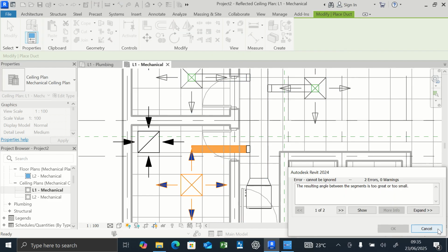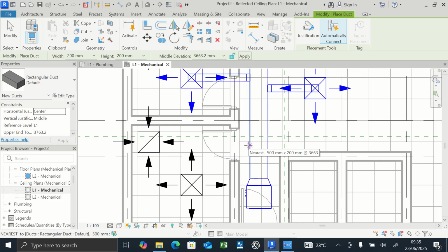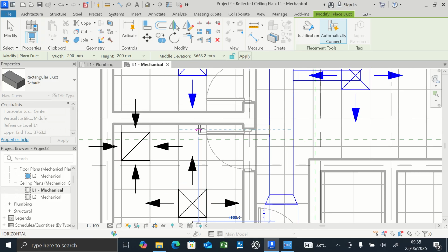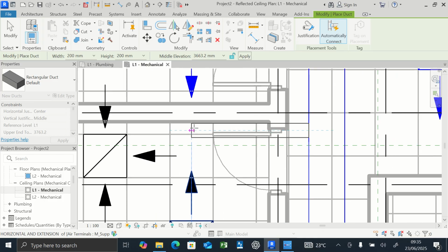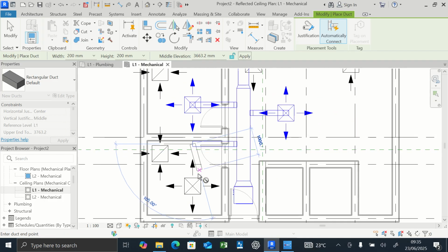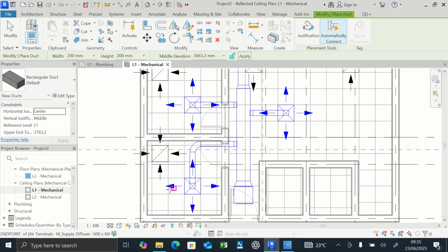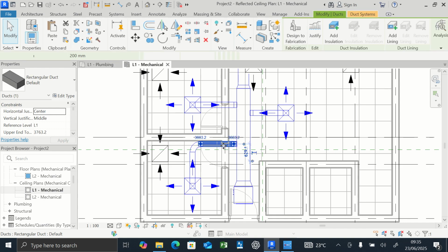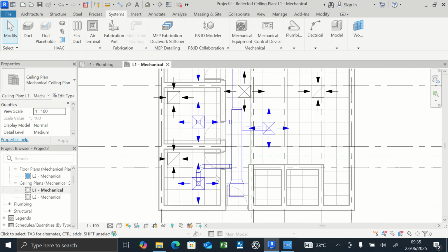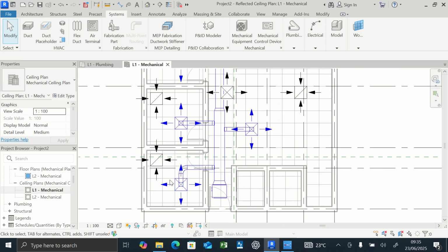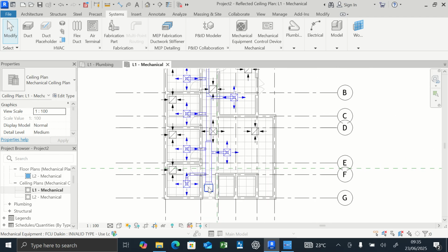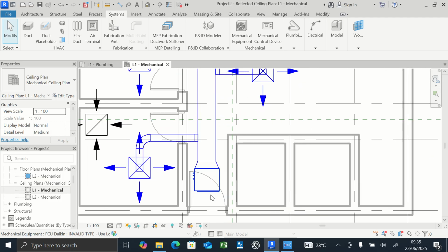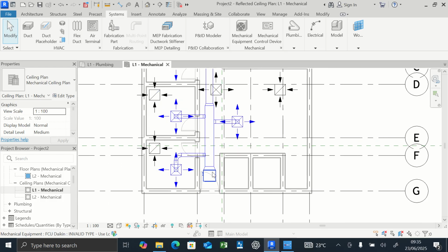From this point, I will draw a duct that allows me to snap to. Let me start from here. Draw a duct to this point. Okay, I draw it, then just bring it straight to the point to connect immediately. You can bring this down by just using your move key and then positioning your duct. So we've successfully drawn the supply duct. Okay, let's draw the return duct.